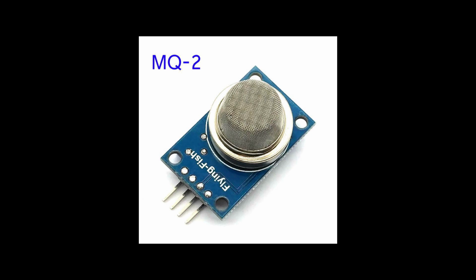The analog pin is also TTL driven and works on 5 volt and hence can be used with most common microcontrollers. So if you are looking for a sensor to detect or measure gases like LPG, alcohol, propane, hydrogen, CO and even methane with or without a microcontroller, then this sensor might be a better choice for you. The applications of the MQ2 sensor are detecting or measuring gases, air quality monitoring, gas leak alarm, safety standard maintenance, and this can be used for maintaining environment standards in hospitals.